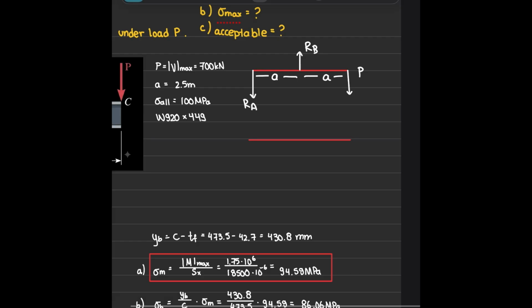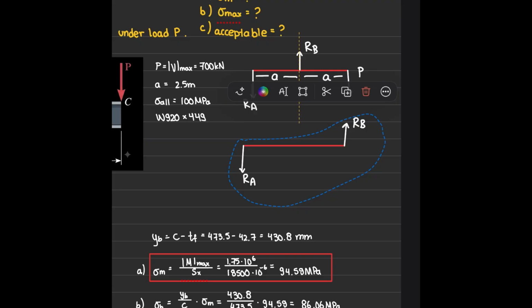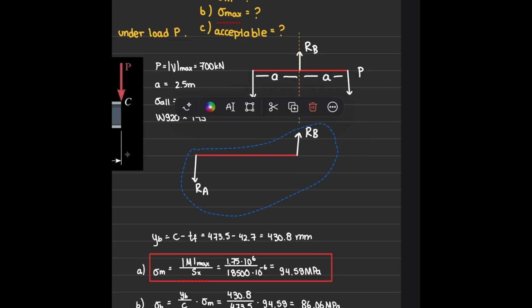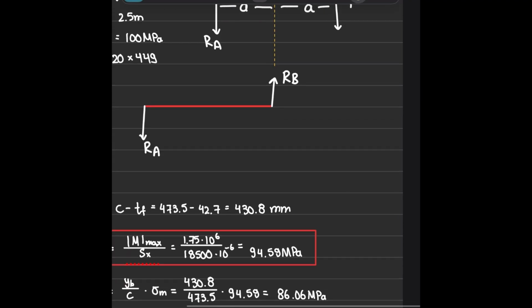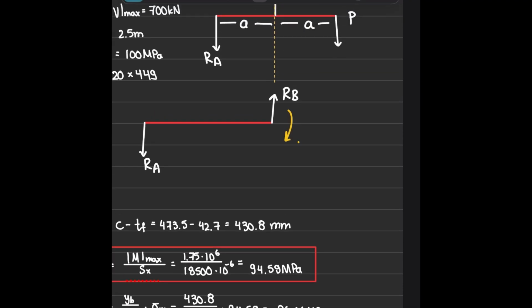And then let's draw one more free body diagram. This time we're slicing it right here. So that just means that we're gonna have a reaction at B. This is kind of confusing, but basically it starts right here, like we cut it in half. When we do cut it, that means that we have a moment now and also a shear force, V. Again, this is A apart.